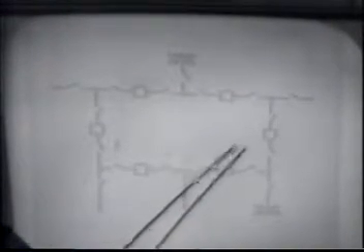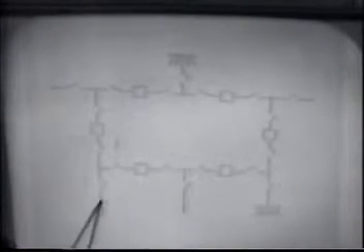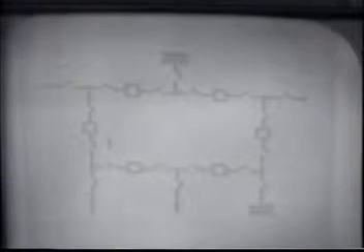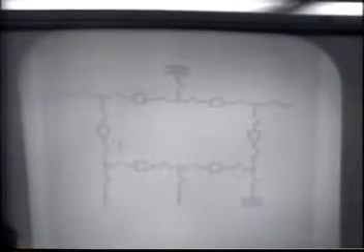The circuit breakers, of course, would be equipped with the various auxiliary devices as we showed on the more developed single line diagram, bushing current transformers. There would be lightning arresters and potential transformers also in this arrangement. However, just to show the basic bus configurations, we've eliminated all of the auxiliary equipment just to show the relationships of the circuit breakers and circuits.